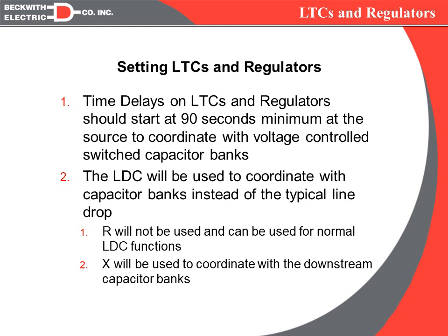And the disadvantage of this is even if you have downline voltage controlled capacitor banks, typically with these short time delays, the LTC will time out before the cap bank will, and you will increase the number of operations on your LTC, and at the same time you'll correct the voltage so that the cap bank will not be able to come in and supply the VAR support it also needs for power factor correction.